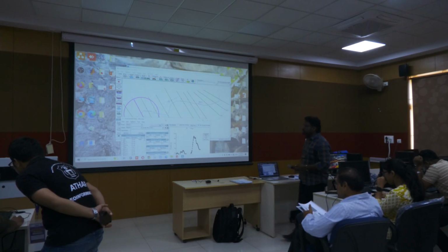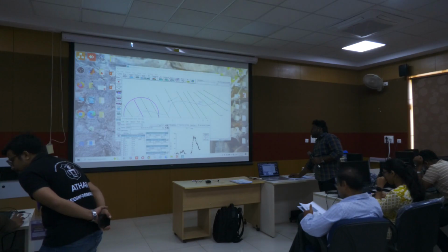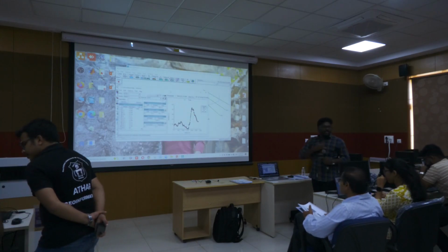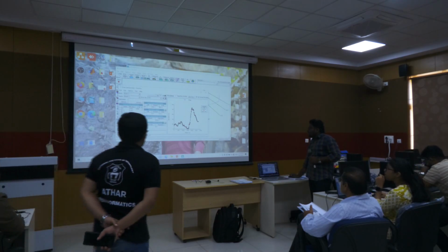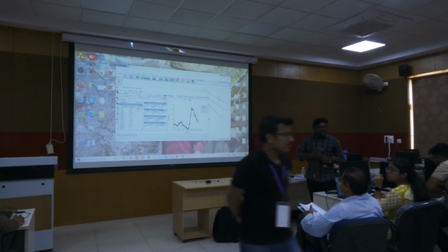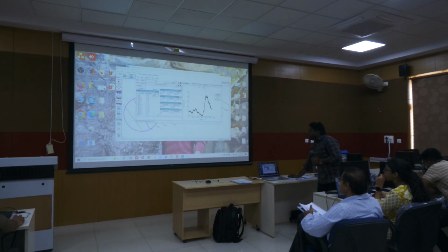Okay? So what I said, along the cross section, we are assuming that the roughness is the same. For that, if you have the data, you can enter at every point along the cross section what the roughness is. But we don't have the data, we are assuming it is uniform. So what we need to do? Select one cross section, right? So here you just see here first.